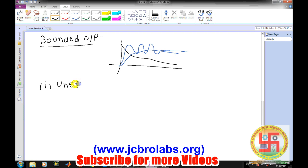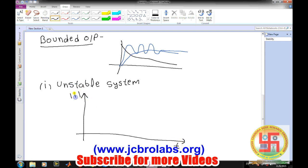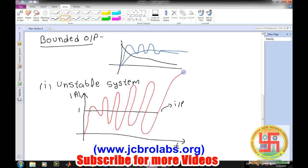One is the unstable system. What happens in an unstable system? Suppose we take a bounded input such as a step signal, and we draw the graph with time on one axis and the amplitude of the output on the other. We have applied a bounded unit step signal to the system, but our response starts and keeps on increasing, and as time goes to infinity it keeps on increasing.